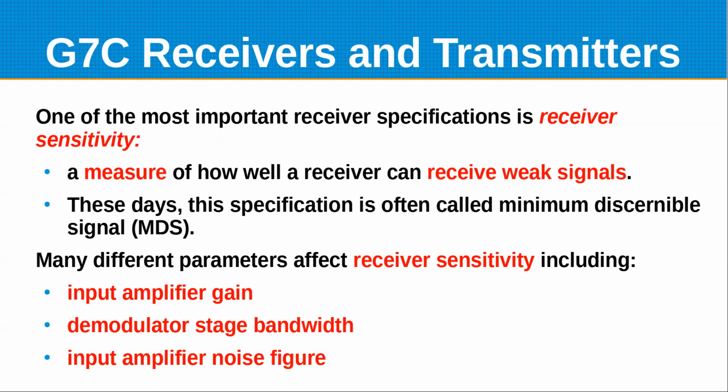So it's partly how low the noise floor is on the receiver itself, in addition to whatever noise you're picking up, and how much gain you have to amplify the signal. In some cases, your transceiver may have some preamplifiers that you can put in the front end to get increased gain besides what you do with your normal input amplifier.